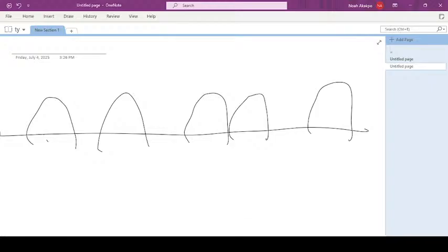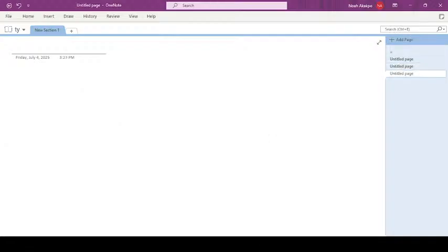So in the positive half cycle, current peaks, like this, that's where current will peak, and that's where current will flow. That's how the flow of current will be documented. And so when current goes positive in the forward bias, it flows, and when it's reverse biased, current doesn't flow. So during the negative half cycle, the diode is reverse biased and acts as an open switch. Now we know that when a switch is open, current doesn't flow.